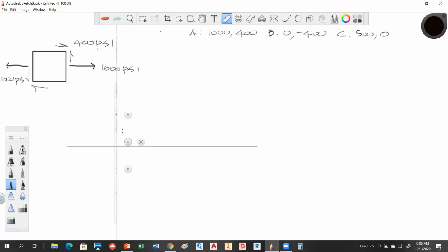Now this is where if you have a straight edge, it really helps, and it really helps you think about what's going on here. So this direction is the direction of normal stress, okay? And this would be zero normal stress, so we're increasing positive normal stress. This would be negative normal stress. The y-axis is your shear stress, okay? And of course, this again is the origin, so that would be positive shear stress, that would be negative shear stress. Okay, does everybody see that?